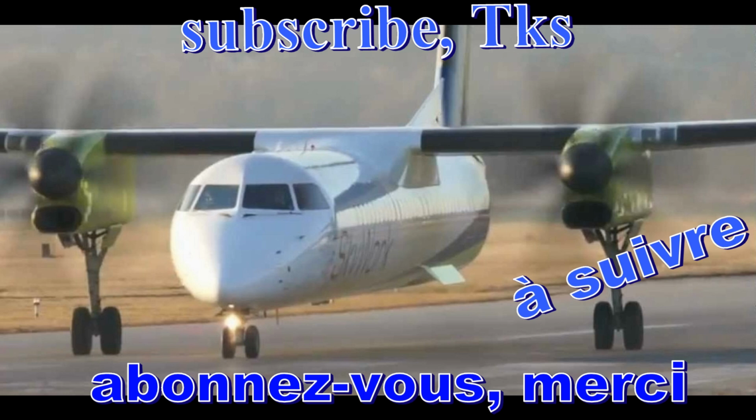This button selects VOR approach mode. VOR approach is almost identical to VOR mode, but should be used in the approach flight phase. It has different tolerances. The indications are approach arm, approach capture, approach track, and approach overstation.